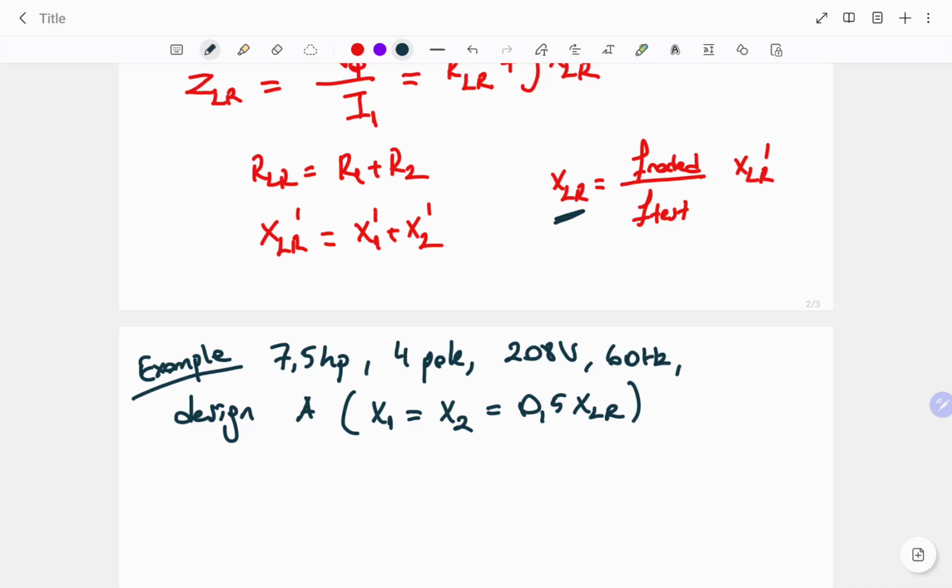So here we can calculate the total reactance in the system, but if we want to separate as X1 and X2, we can check the design type of the machine. We have a Y connected induction motor, and its rated terminal current is 28 amperes.